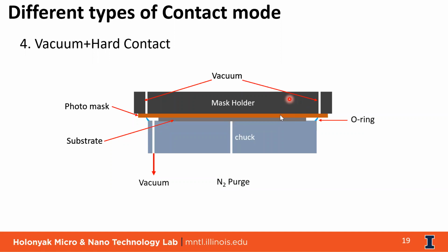So which can seriously affect your spin coating. So the HMDS, what it does is when you coat a thin layer of HMDS on top of your wafer, it will form a methyl group on the wafer surface. So it will chemically modify your wafer substrate. So that's the one improving the adhesion between the photoresist and the wafer.